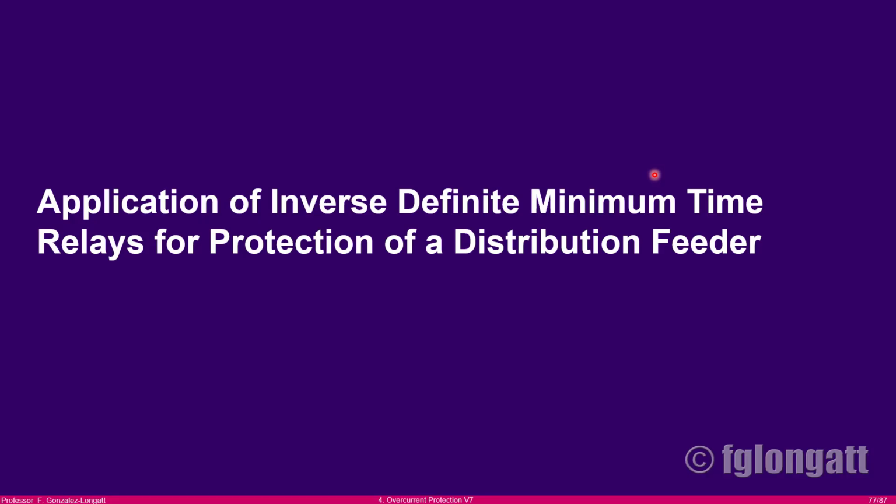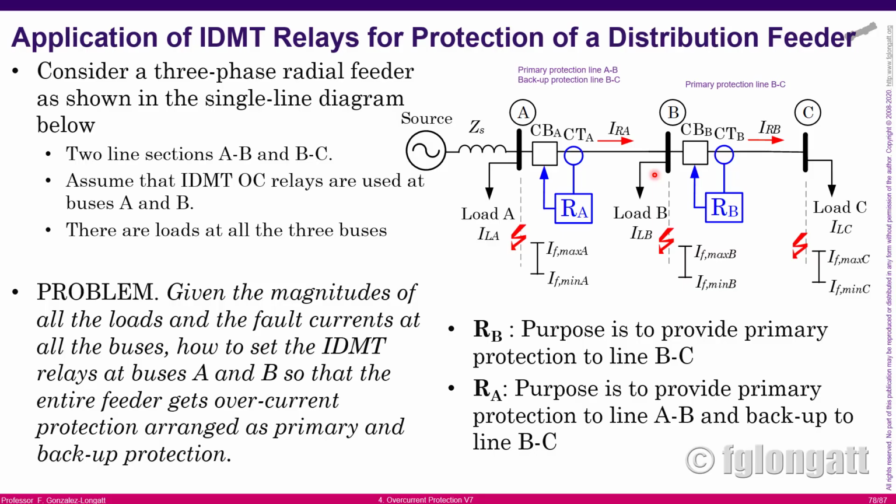Okay, next case. Now let's work with time delay relays, non-directional overcurrent relays. What I will do now is use inverse definite minimum time relays for protection in a distribution feeder. In this case, the situation is similar to the one that I presented before.